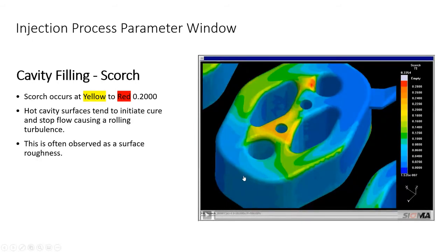And again, designed for manufacturing. Before they made their first molded part, they knew what their defects were going to be. They changed the way the mold was going to be built, the way the cavity configuration was designed. And because of that, they were able to solve these problems. All right.